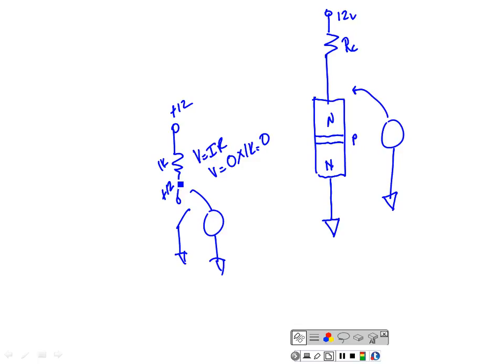It has no current flow in the circuit. If there is no current flow in the circuit, nothing in the circuit is dropping voltage. So all your wires in the whole circuit are acting like straight pieces of wire, and it gets up to that open and the voltage appears across the open. So if I go over here to this light switch and I measure across these switches, the ones that are running these lights, what is it going to measure?